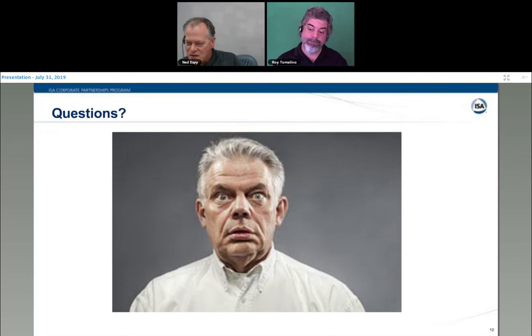Yeah. So here's a question about a dual RTD. So obviously you can only check it one at a time, and then simulating the rest of the loop. I don't have a lot of practical experience with dual RTDs. I mean, you're using them different ways. Some people are averaging the signals. Some people are looking for a deviation. If there's a deviation, that's a highlight that something's going on with at least one of the probes.